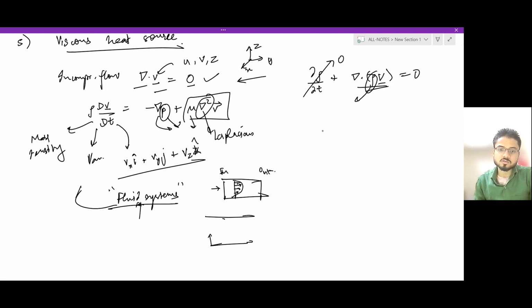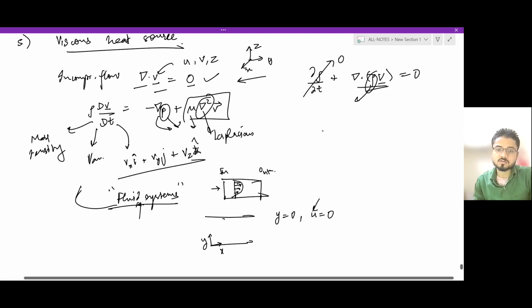And in this flow through a channel, you had to somewhat do this, that, for example, your coordinate system starts right here. Then what you'd be doing is at y equals 0, you introduce a no-slip boundary condition where you use the x component of the velocity field.